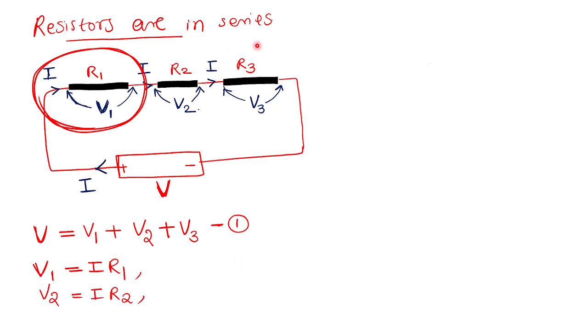Similarly V3, Ohm's law says that V3 equal to the potential difference between these 2 points, V3 equal to the current into the resistance of the path. We studied that potential difference between 2 points is equal to current into the resistance. That we studied in the earlier classes, which is actually Ohm's law.